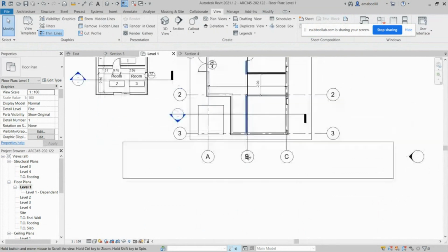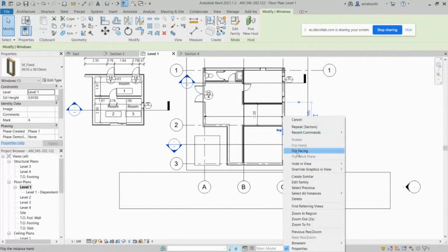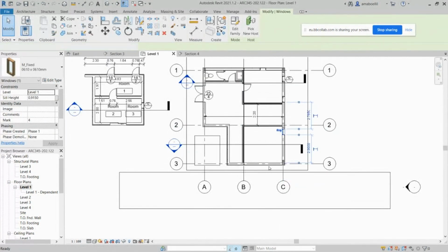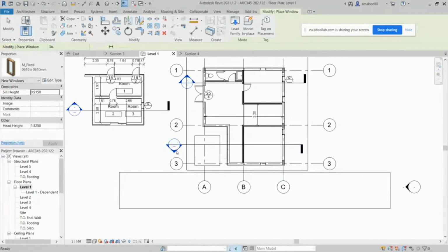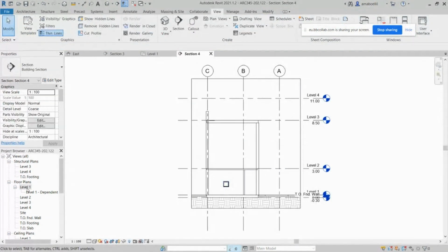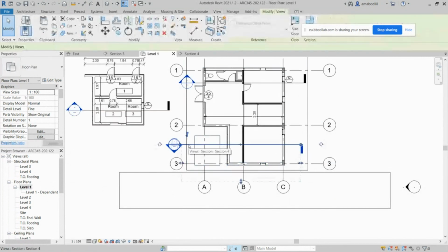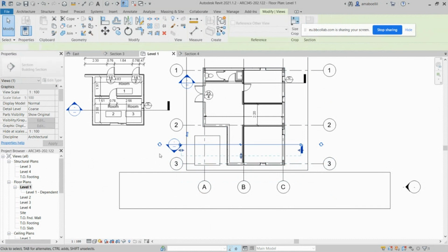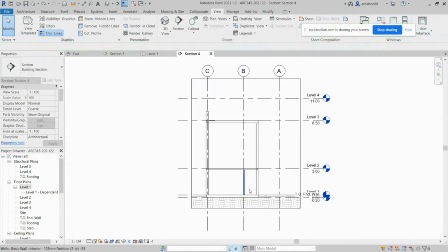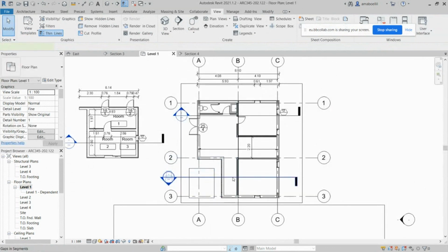So if I do the level 1 again and I create a wall and a window, and I place it here, and I get to my elevation, I see the little window here. If I want to crop that and don't want to show the back walls, I can come back to the level, and instead of showing the whole depth, I can drag this to the inside and double click on it. It will show me just things that I'm cutting through, limiting the depth of what I want to see.